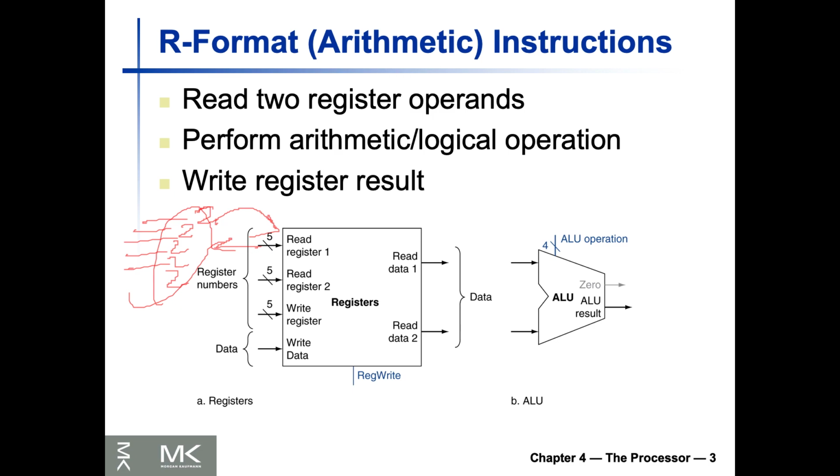And just like I mentioned in the previous lecture, the convention is that we are doing the writes on the edge triggered clock, right? So all the values must be available before that. Otherwise, we're going to run into a read after write or write after write issue.